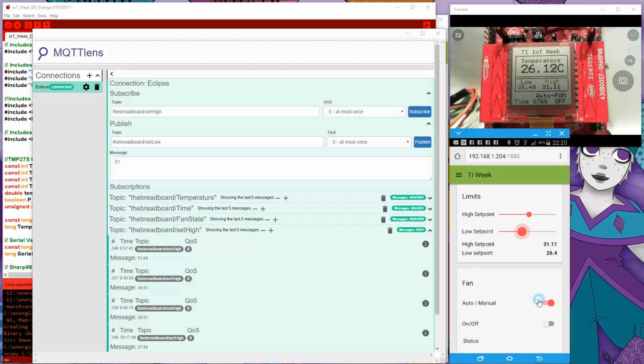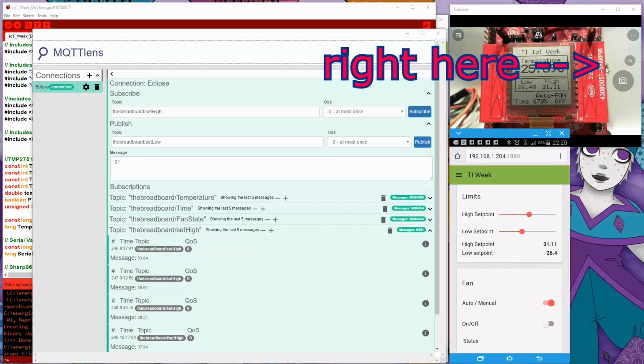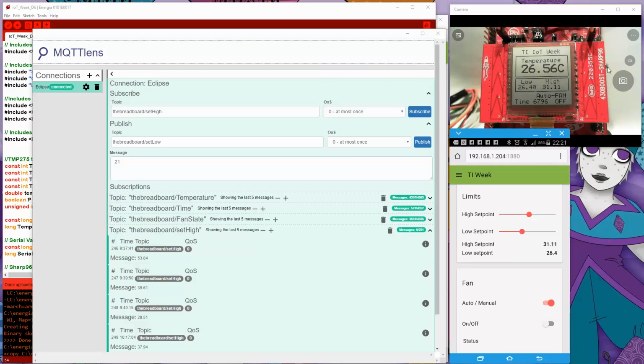So what I was going to show you was if I turn this on, it's going to have no effect right now. Right? It's had absolutely no effect. Turn it back off again. Now what I've also done, I don't have the fan connected here because I'm actually in my office with all of this hooked up, but just on the edge here you'll see that I've actually hooked in a white LED. So if right now I heat this sensor up again and take it back to the on, you should see this come on.